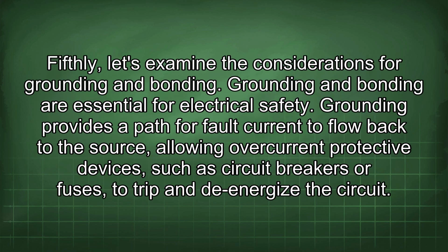Fifthly, let's examine the considerations for grounding and bonding. Grounding and bonding are essential for electrical safety. Grounding provides a path for fault current to flow back to the source, allowing overcurrent protective devices, such as circuit breakers or fuses, to trip and de-energize the circuit.